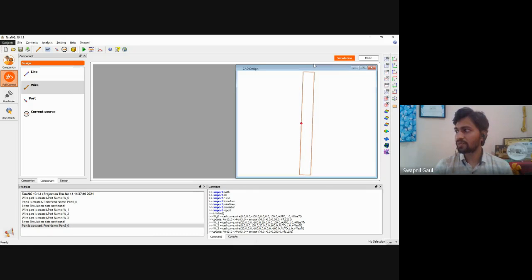But if we try to feed this folded dipole antenna with coaxial line, it will cause some problem. It will not match. If you have seen the old Yagi antennas, there is a folded dipole antenna element as the driving element, and that element we didn't use to feed with the coaxial line. We used to feed it with that parallel cable wire. So we need to change the wire for feeding that antenna, and that particular wire has an impedance of around 200. So we can make this kind of arrangement.